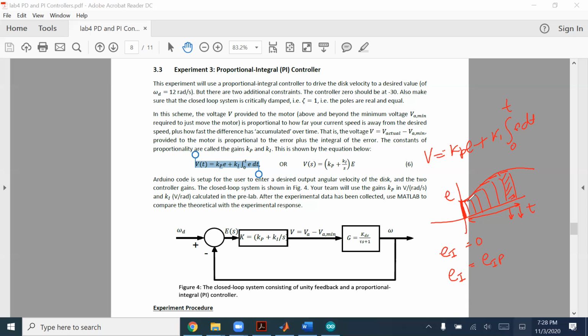So this unshaded region is the previous area at the previous loop time, and the total is the error integral right now. So the error integral right now is equal to the error integral at the previous time plus this extra shaded bit. And what is that extra shaded bit? It's E multiplied by delta t. So that's how you can implement integration. It's a running integral.